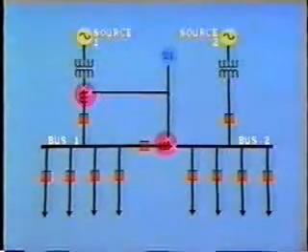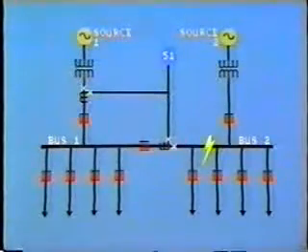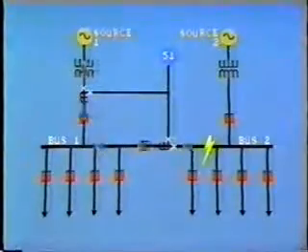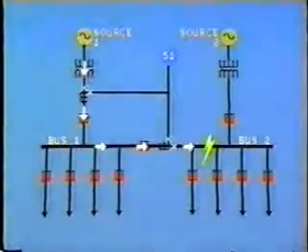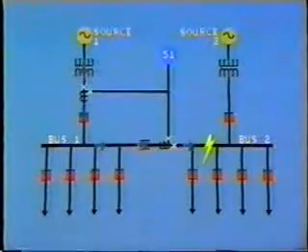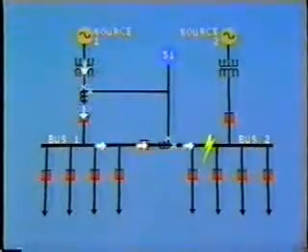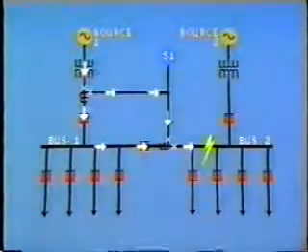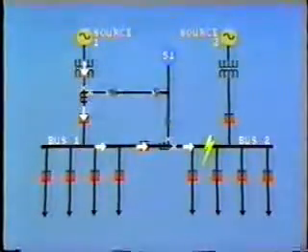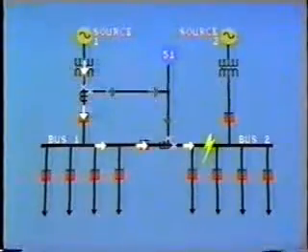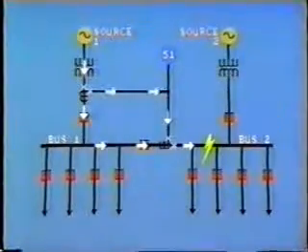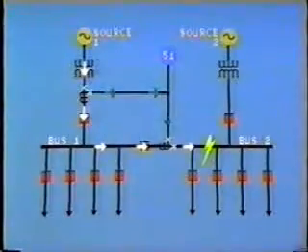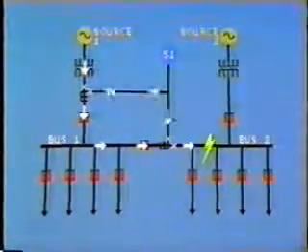which are in parallel. If a bus fault occurs on bus 2, a heavy fault current will flow from source 1 into bus 1 and through the tiebreaker into bus 2. The CT currents will be subtractive and therefore will not operate the overcurrent relay. Of course, the CT currents will not be identical because there is some current being supplied to the feeders. The setting of the relay must take this into account.